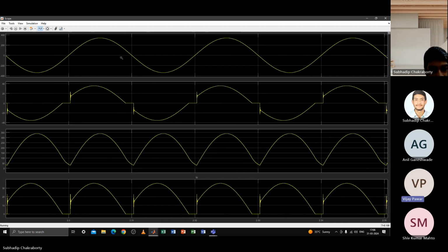Second observation is that they are in phase, I think, but do you see distortion is there? Just see the crest of the sine. Do they coincide? That is, do they appear at the same time instance, or is there some shift between the two sines? Yes, there is some shift. If you see carefully, then the current waveform is distorted, agreed, and also the input current I am talking about is slightly leading in nature, right? It is appearing before the voltage, the crest.